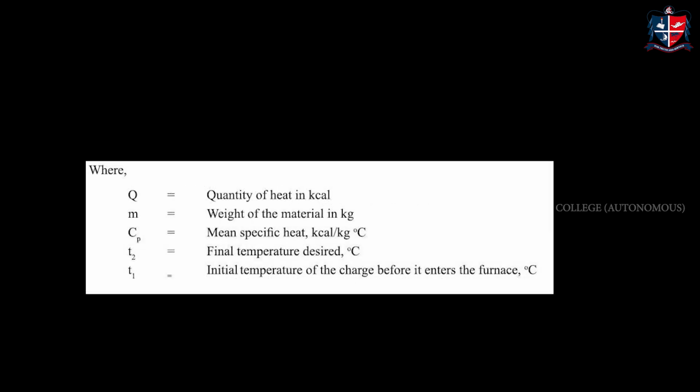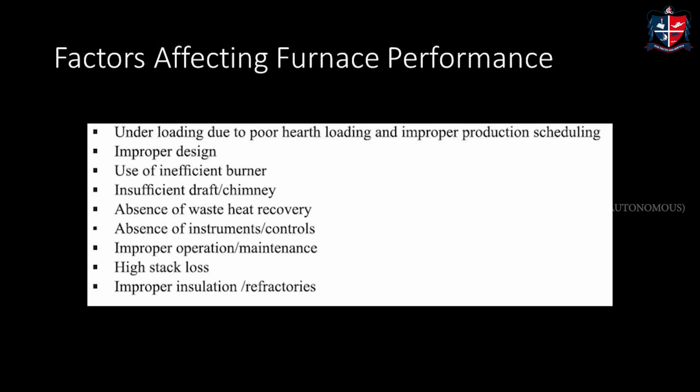Then what are the different factors that will generally affect the performance? As I said, there could be many factors. One such is improper design. If it is not properly designed, it could affect your overall efficiency. Then we have the absence of waste heat recovery. As I said, the flue smoke can be used again. If you do not use it efficiently, the performance gets affected.